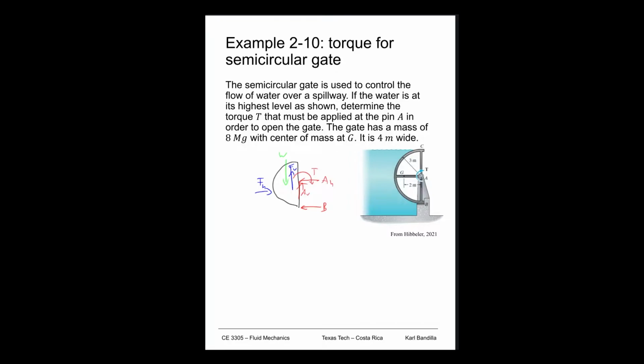All right, so I think we'll start by figuring out what the two forces are based on the water pressure. And remember that we can do that by just doing, for the horizontal one, a projection. And for the vertical ones, we have to see what the weight is of the water that's sitting on top. Now, to see that, we have two different parts. If we think about our little setup here, I'll just draw a line in here. All right, we can say we have the part up here, where we get the water pushing down. Right, that's what we have.